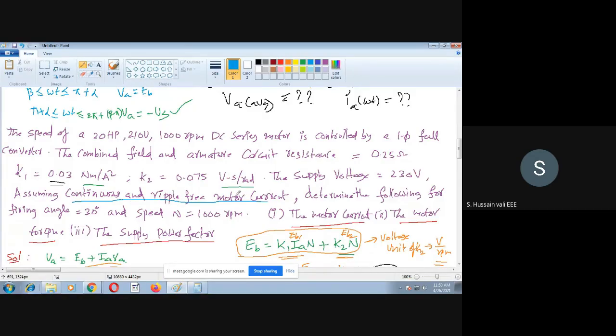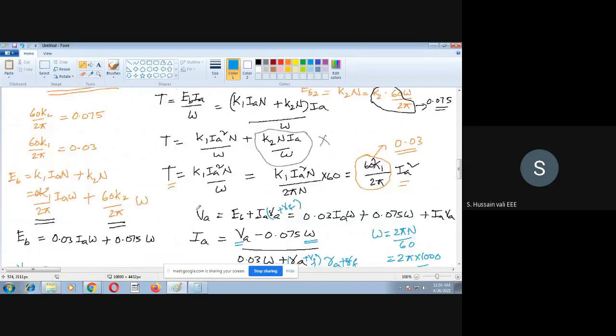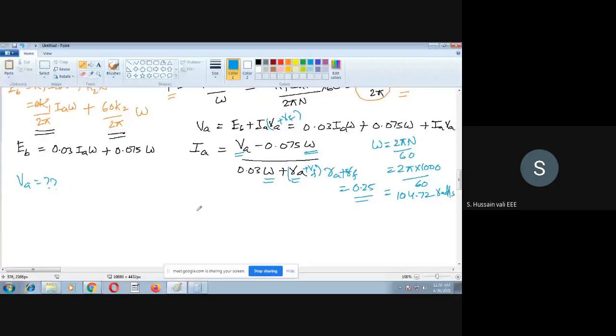I hope we can understand this now by this time. So it's a continuous conduction, so you have to take the continuous conduction. In the continuous conduction, what is the VA expression? If you recall, it is 2Vm by pi into cos alpha. It's a direct formula we got already. We derived this. So 2 into 230 into root 2 divided by pi into cos.